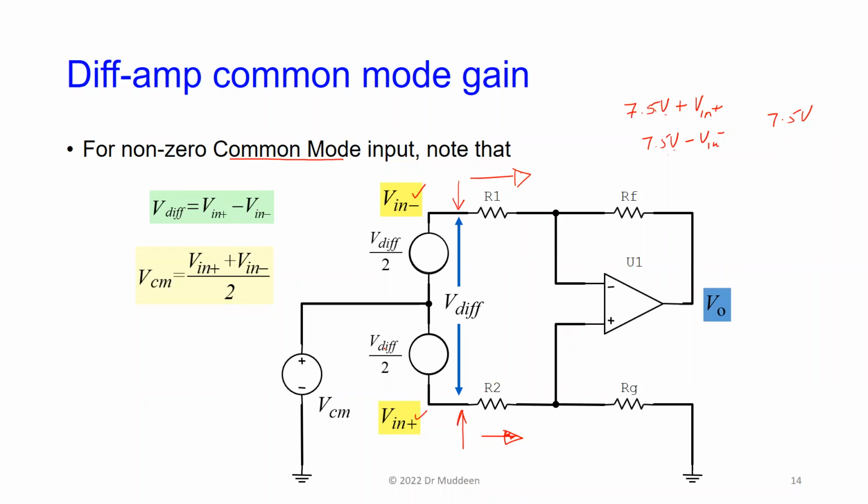So we do a little bit of a model. This is Vdiff, and we say we have a common mode voltage, which is the thing that we don't want. How we're going to express it is that our differential voltage, we split up into 2 bits. If you ignore this for the time being, Vdiff is composed of 2 things, Vdiff over 2 in value each, and then at the junction of the 2 of them, we add our common mode voltage.